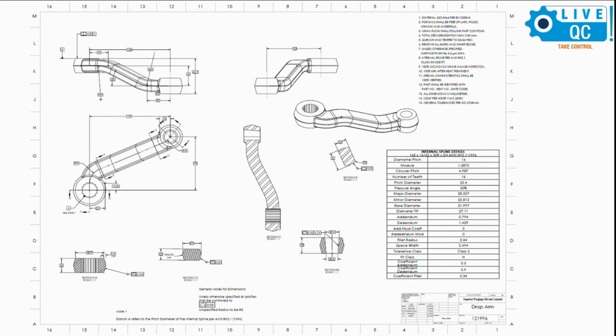So you look at all the parameters which are sitting over there. Now you need to monitor all these parameters, not all the parameters. Then your cost goes up, appraisal cost goes up. Only those CTQs. And which are the CTQs? DFMEA should tell you, right?